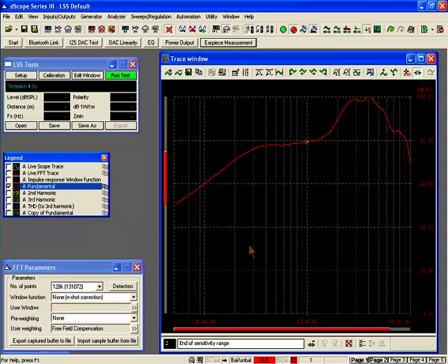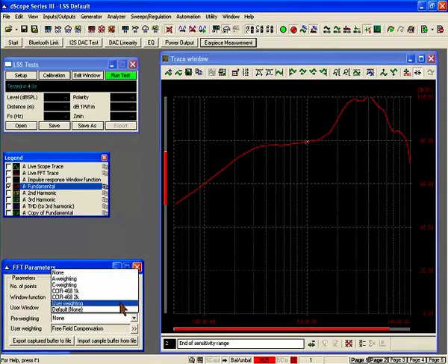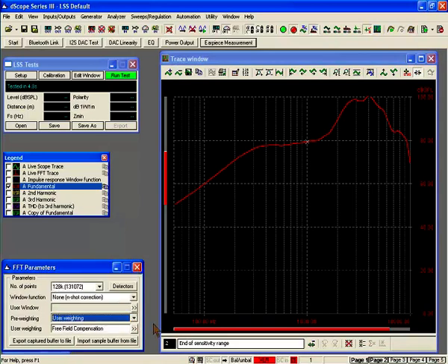So you might actually want to take that acoustic resonance out of the measurement and just simply quantify the performance of the headset itself. And we can do that by selecting a pre-weighting filter here that has been designed to compensate for that ear canal resonance in the ear and cheek simulator.